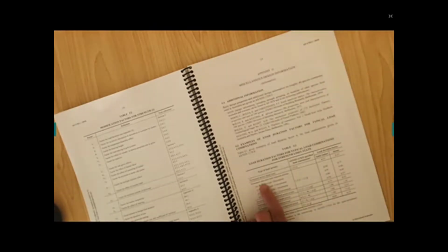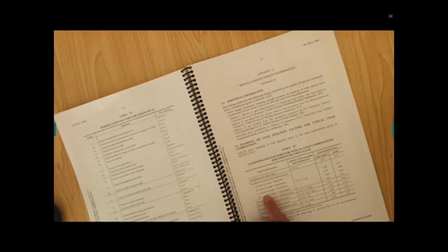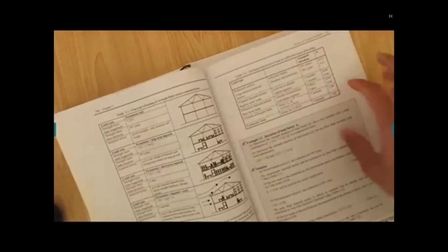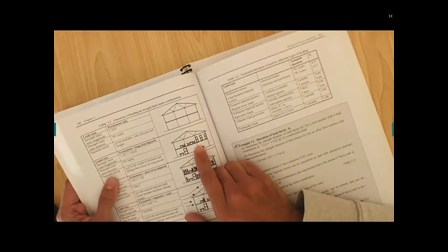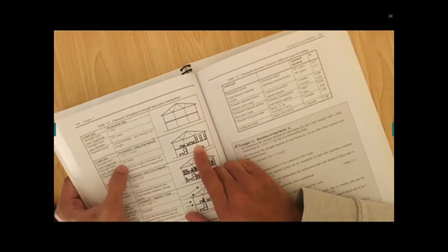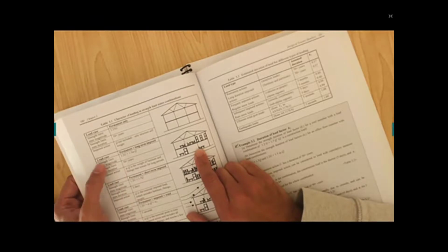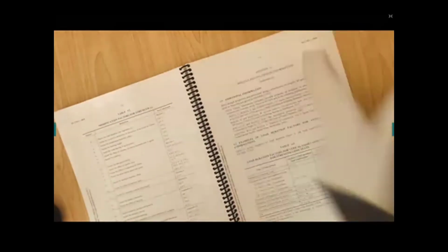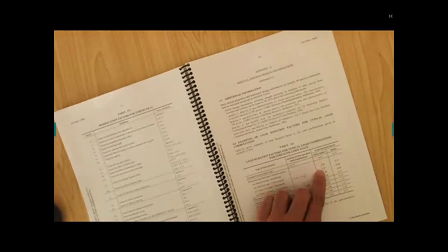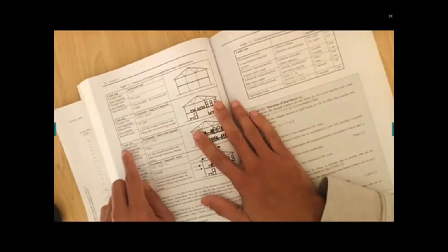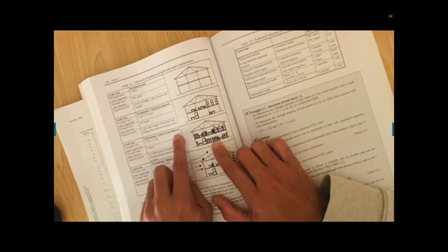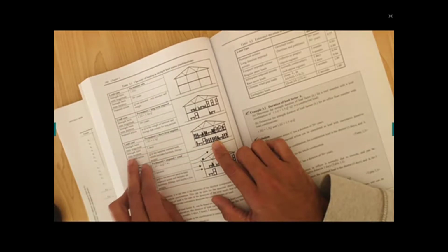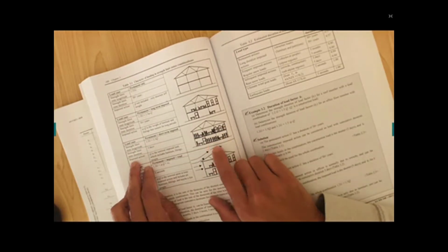Now then you have permanent and short-term load, roof live load, roof and floor load, and this one says that you have dead load and you have live load, some occupancy as well, some short-term factors, and you have 50 years, and again this one. So in that case, you have different load cases, and for those load cases you have different values given to you here. Now the third one, that load case, is for 5 days. This is the typical case where you will have a normal short-term imposed load. Strength limit state, short-term, says you have a dead load and you have five days.